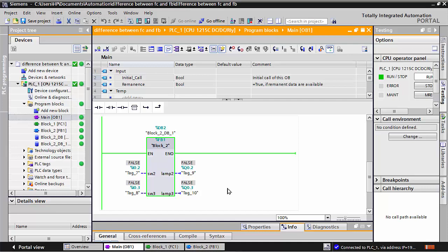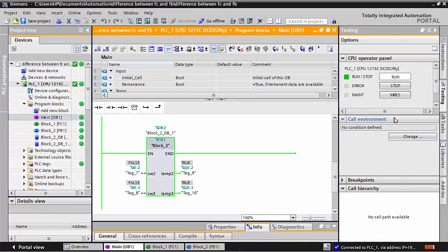For example, think about I give the signal. Now I removed the signal. Here you can see I0.2 or I0.3 or anything does not have a signal. Here Q0.2 and also Q0.3 are in set condition. And in that condition, for example, if the power supply is gone, think about the power supply going to off condition or error condition.